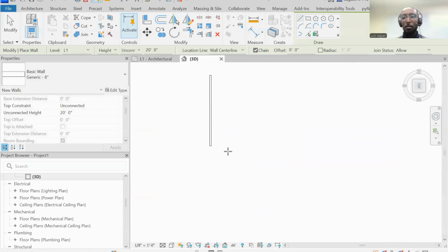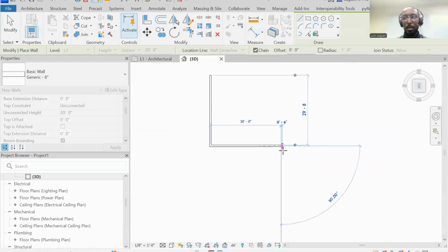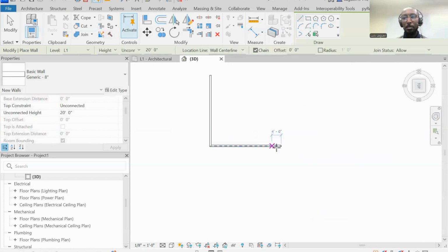Now let's say that I wanted to draw another wall because I'm making an apartment, right? I need the next wall to be 15 feet, or maybe 30 feet. Maybe it's a bigger apartment, right? So I go over here. I can extend this out 30 feet, or I can type in 30, which is usually the faster option. Press enter. It extends out, and now I have another option.